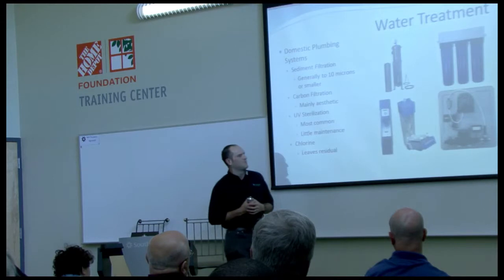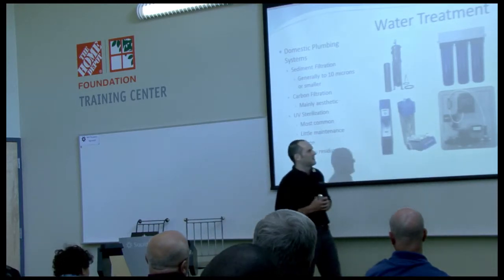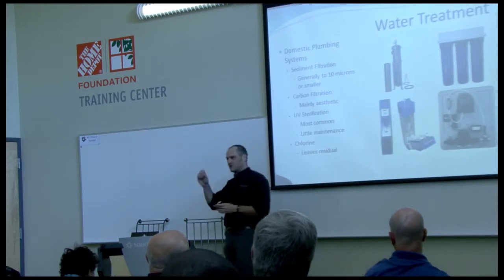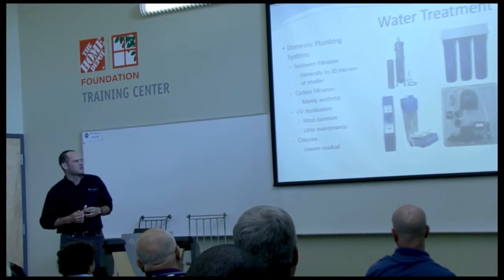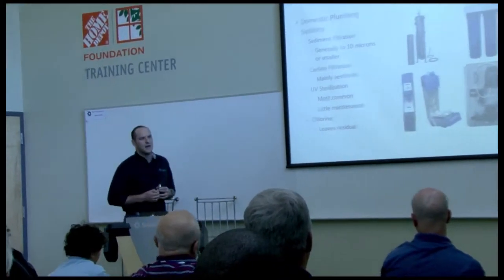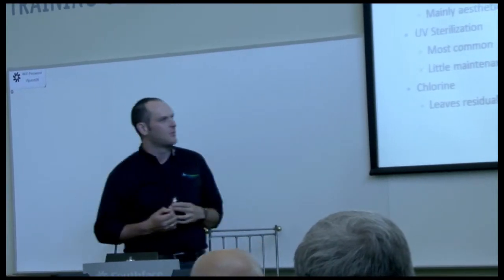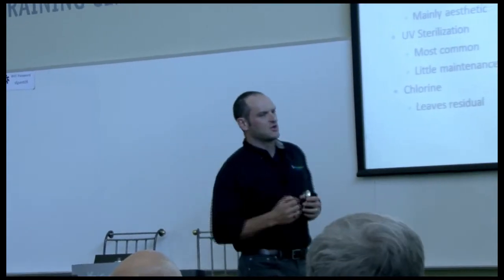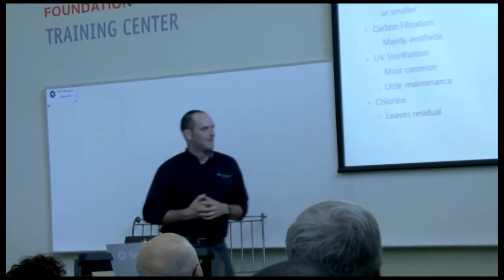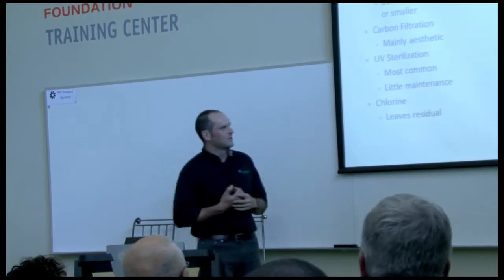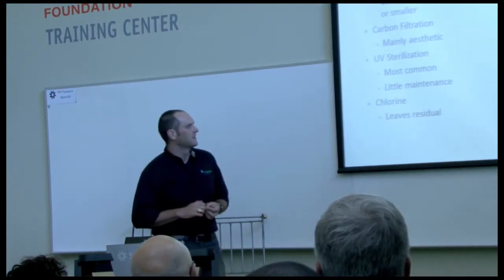The other common thing we see would be chemical injection, chlorine injection. This little board would do something like that. Basically you're actually injecting chlorine into the water system. We don't see quite as many of those. It requires a lot more ownership. Under-chlorinated water can be just as dangerous as over-chlorinated water. So you have to dial in just the right amount, make sure you're getting just the right amount of chlorine in your system. And you have to handle a dangerous chemical, things like that. So we don't see them implemented quite as much, but fairly regularly.